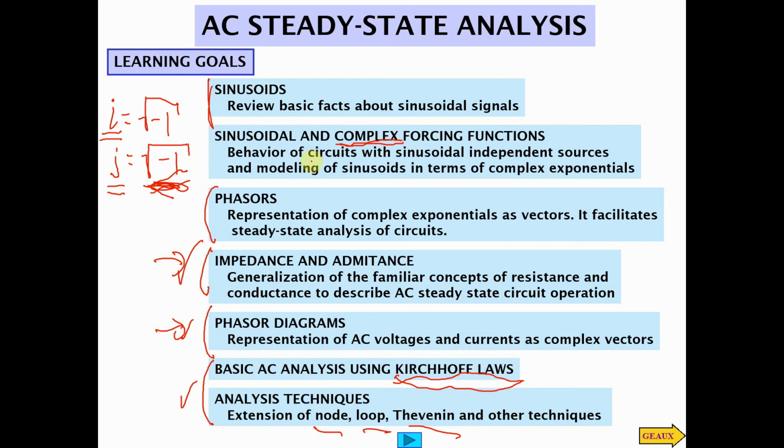And if you have a sensitive sensor, a strain gauge, for example, and you have a shaft in a noisy environment, a lumber mill maybe, you've got to build sensors that run with all that sawdust and sound and vibration and electrical noise. Big motors have coils in them, and they generate pretty big magnetic fields that can be picked up by sensitive electronics.